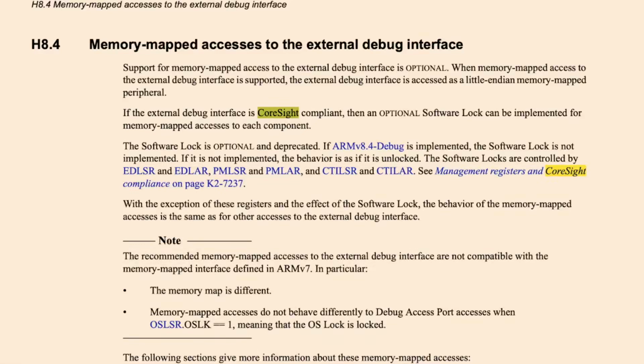Now, the external debug interface, it turns out, is pretty much just a different way of accessing the same functionality that Ian used in his self-hosted kernel debugger. So in the self-hosted debugging interface, you write to these debug registers using MSR instructions. The external debug interface provides very similar functionality. It's probably the same debugging hardware under the hood that you're driving, but the interface to access these registers is via MMIO rather than via executing MSR instructions.